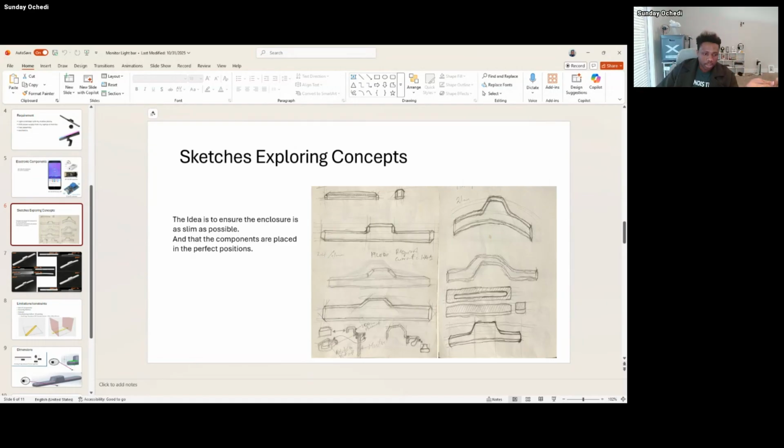And some of the common analysis when it comes to designing a part, especially consumer products, are consistent analysis that you need. You have drop analysis. That's something you want. You have the stress analysis to ensure that this can withstand whatever stress is acting on it. Or you have your draft analysis depending on the manufacturing method you're using.